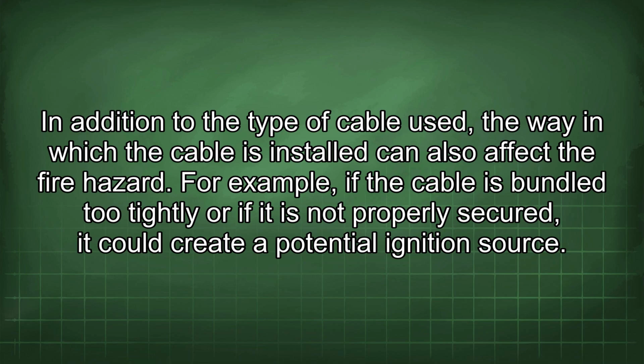In addition to the type of cable used, the way in which the cable is installed can also affect the fire hazard. For example, if the cable is bundled too tightly or if it is not properly secured, it could create a potential ignition source.